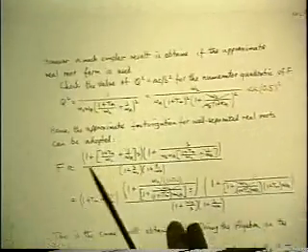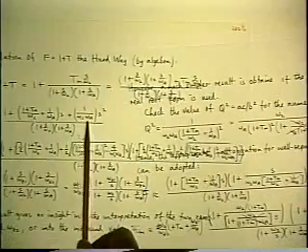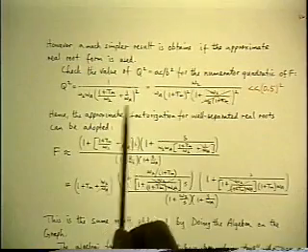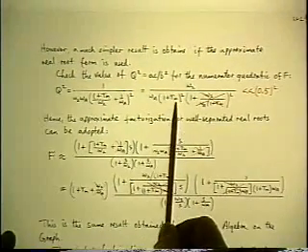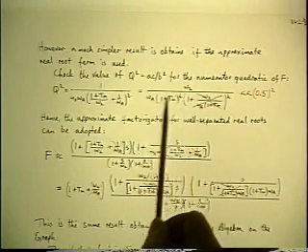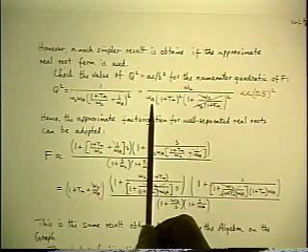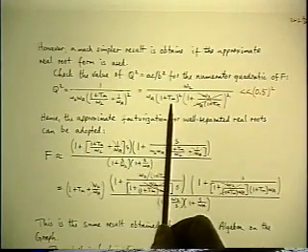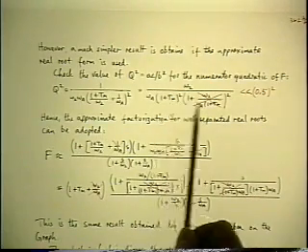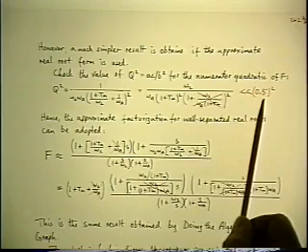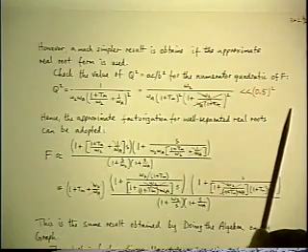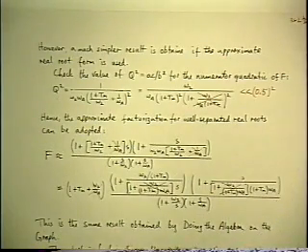which is the coefficient of the middle term. And well, in terms of the A1, A2 coefficients that we've had before, the q is found in terms of those two coefficients, and this is what it is. And it's easy to see right away that it's a very small number, because it's the omega 2, which is 30 hertz, divided by omega A, which is 2 kilohertz, and then divided again by the square of the midband value of the F, which is 11. So the resulting number comes out to something very much smaller than 0.5 squared. So this validates the real root approximation extremely well.